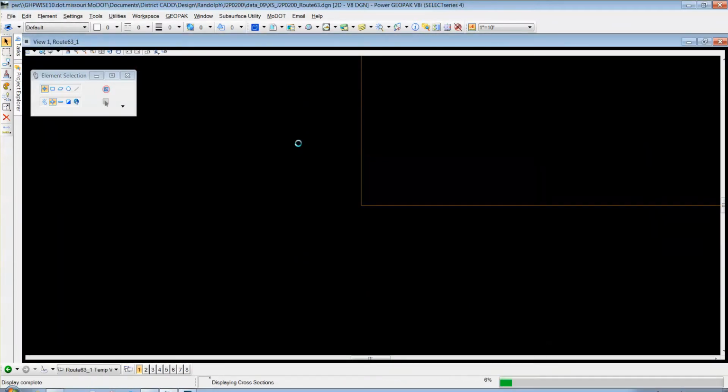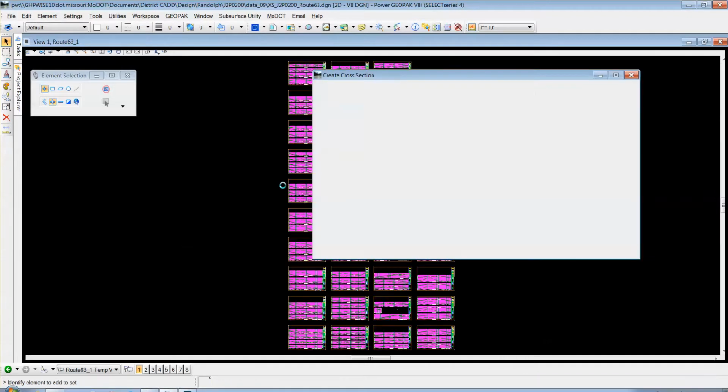And you know, we did the individual Route 63 cross sections. We didn't change the design stage to a tighter design stage. So now we're doing it where our template drops are much closer. Still doing the same amount of cross sections, but it's a lot less interpolation on this part. So as soon as this thing gets done processing, we will have some cross sections to work with.